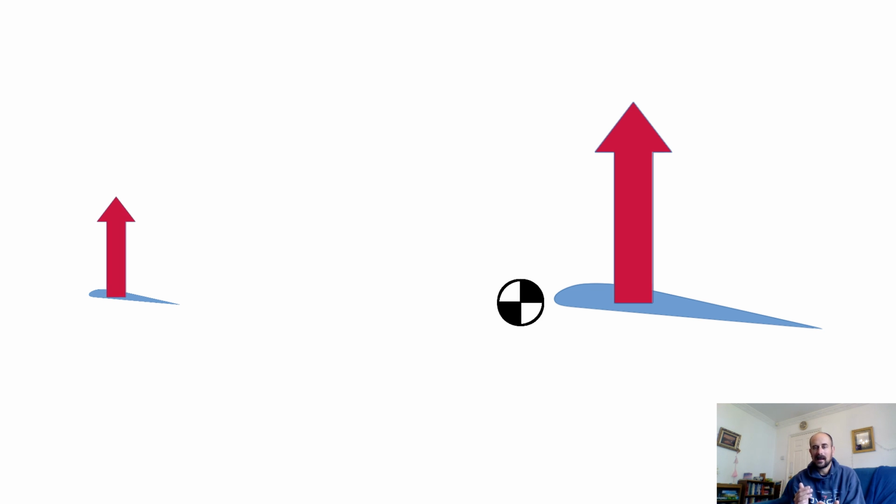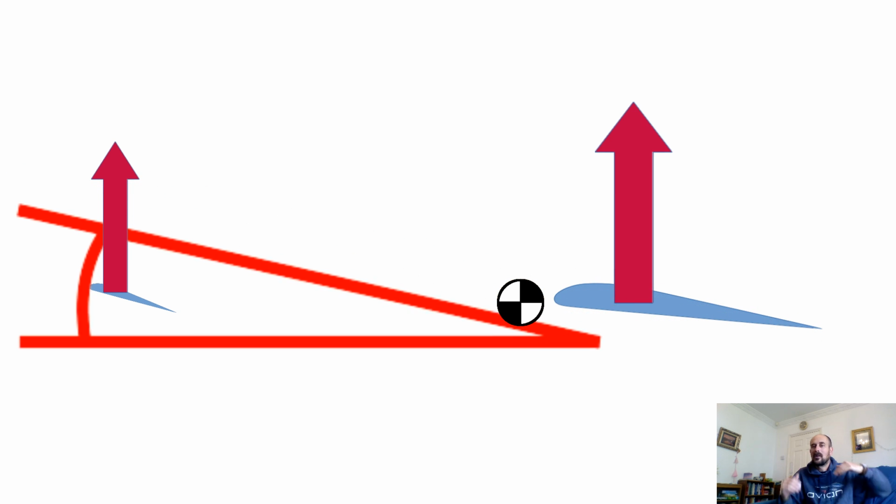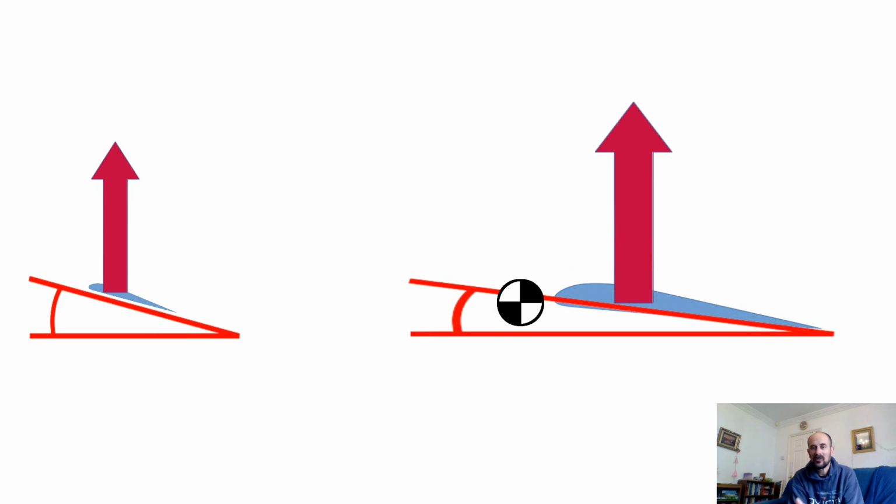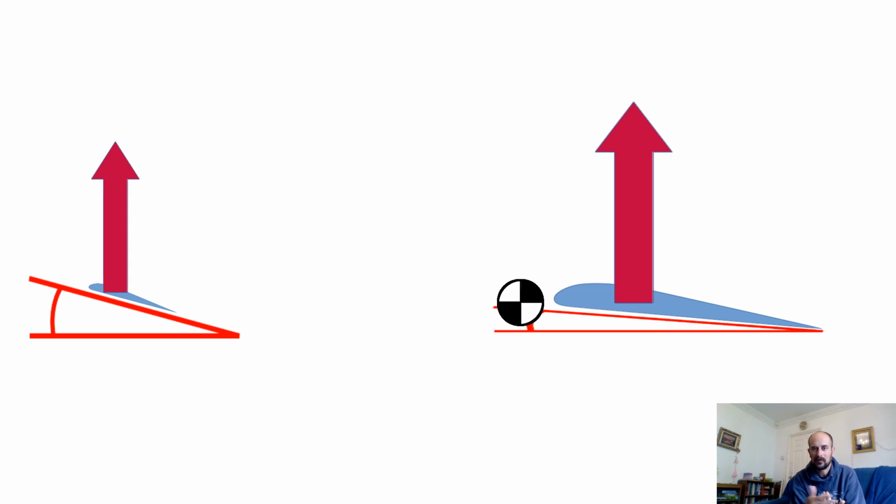And the way to do that is to increase its angle of attack, so to mount it on the fuselage at a higher angle than the main wing, which is exactly what's done on any canard aircraft that's designed to be stable. Some fighter jets have canards, they're not designed to be stable, the electronics stabilises them, but for things like the Rutan designs, they'll always have the front wing set at a higher angle than the rear wing. So the front wing is generating more lift per unit area than the back wing. In other words, it's flying at a higher lift coefficient than the rear wing is.